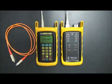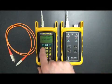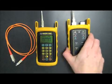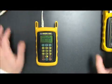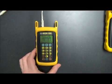Now, the start menu shows you a couple different options. The option for setting up the meter to do a test is called Link Wizard. Link Wizard is simply the process by which we're entering our link information. So to start the process, we press 1. And then for this particular part of the procedure, we will not need the light source. So I'm going to set that aside for now so I can zoom in on the micro-owl display so it's easier to see.